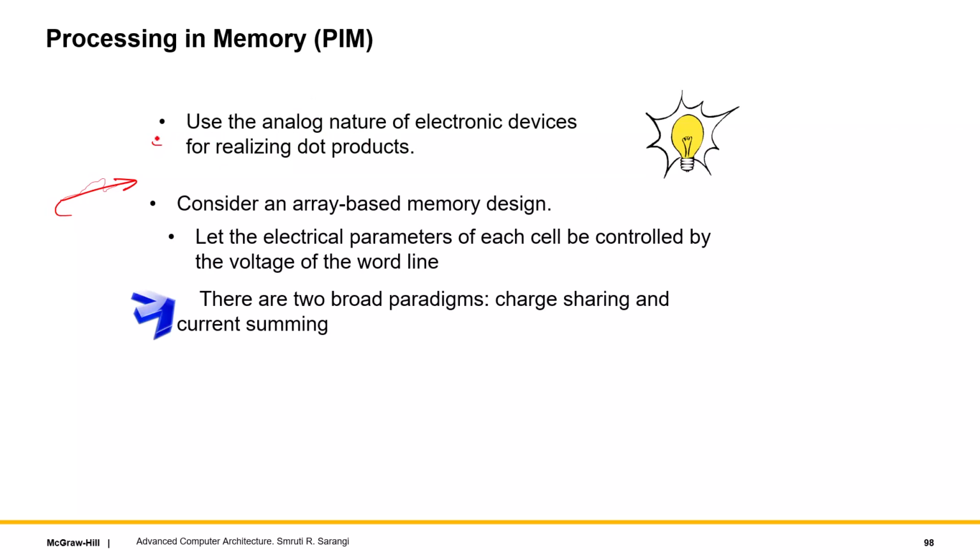So instead of using digital circuits, we can use analog circuits where we will use the electrical parameters of the devices to actually realize a multiply and accumulate operation. What's the main operation? You have a bunch of filter weights, a vector basically, because I'm converting, even if it's 2D or 3D, into a vector, kind of like going this way.